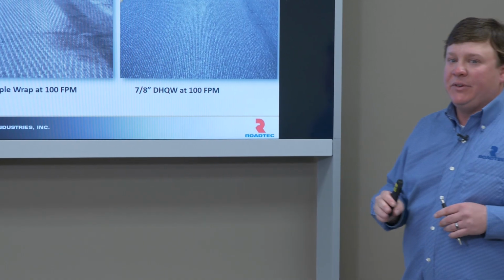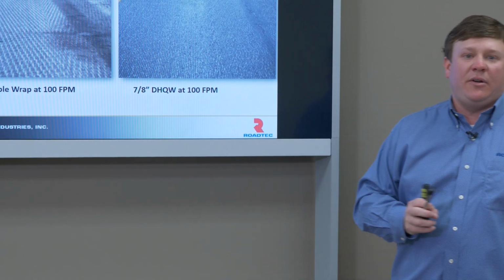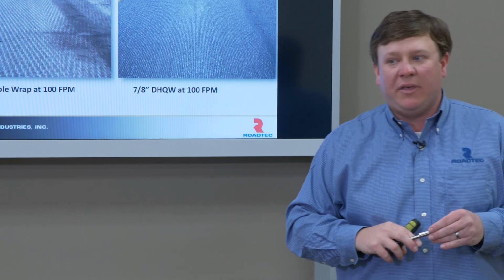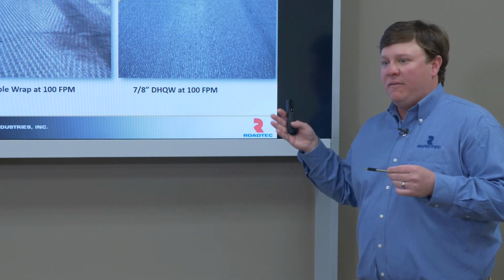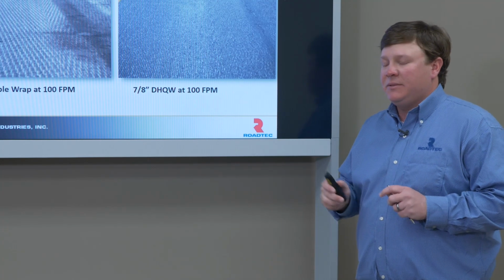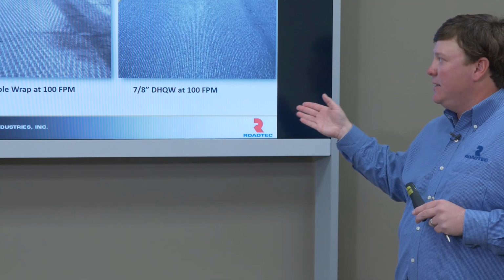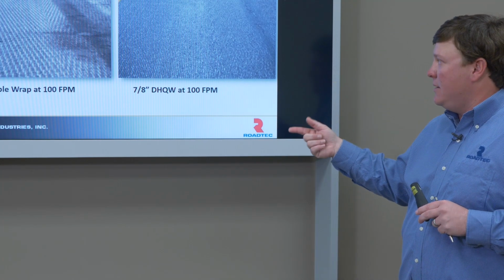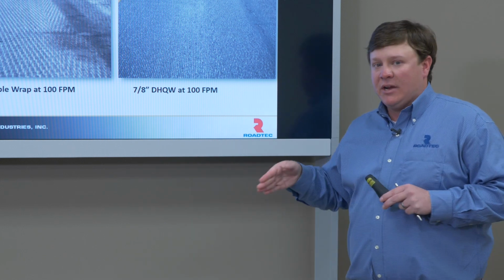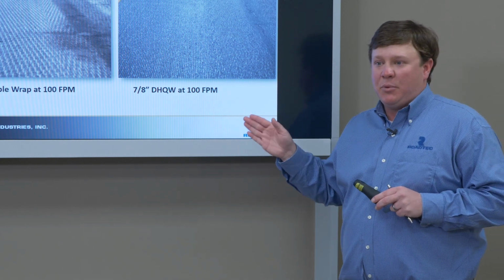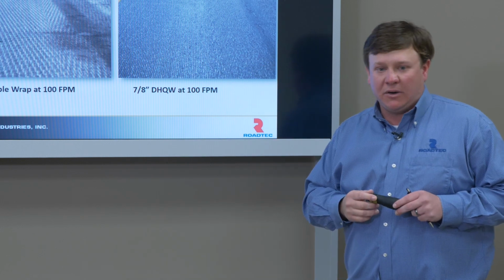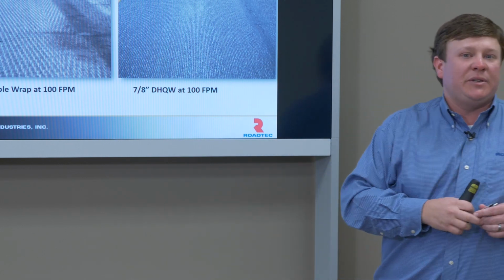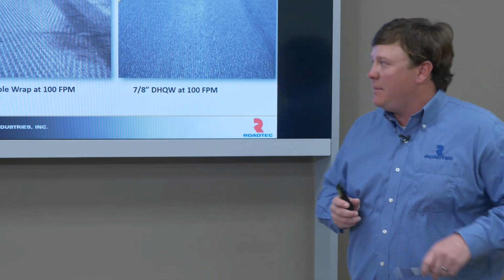Now, the double hit drums don't come without their own limitations, so they're not a solution for everything. This pattern really only is obtainable up to 4 or 5 inches. So at deeper cut depths, you would not get the benefits of it. At shallower cut depths, it's a nice tool to allow the contractor to achieve a higher production level, and everyone else, we get the smooth milled surface. But it's not a solution that can be applied to every project by any means.